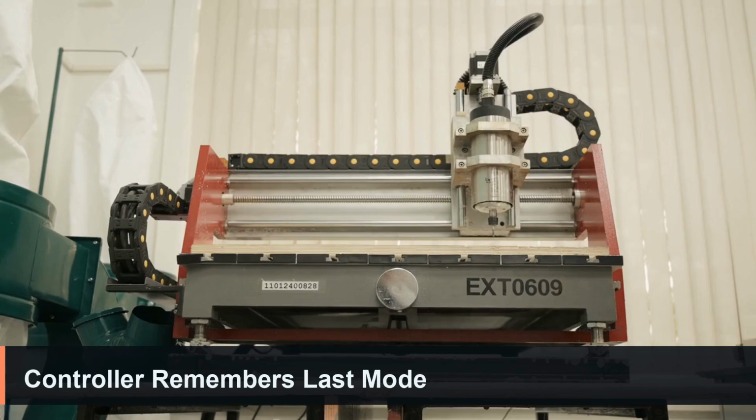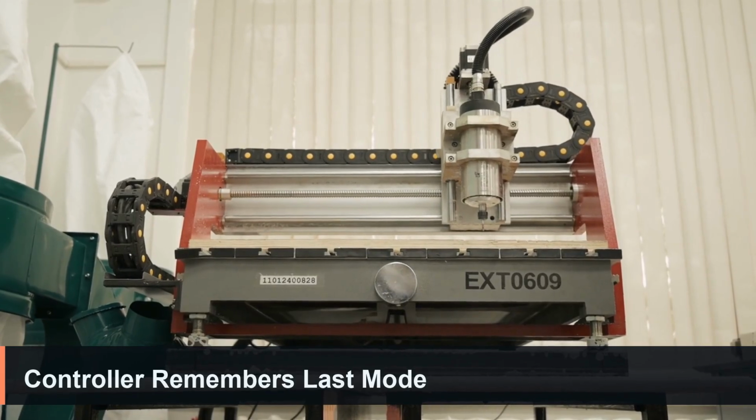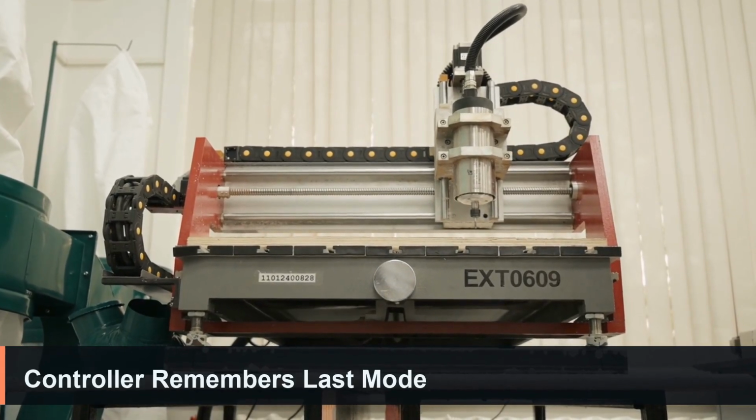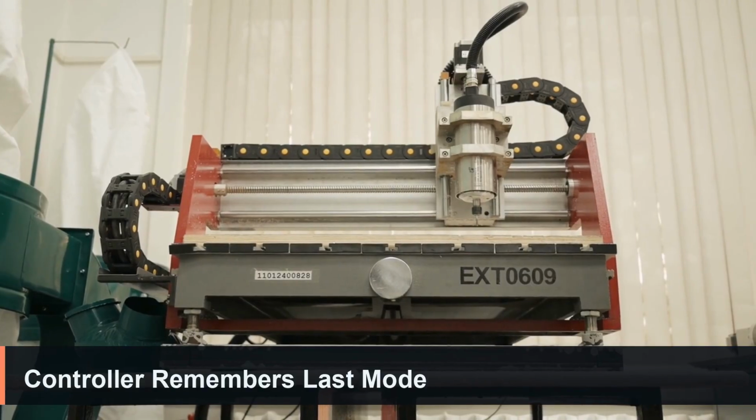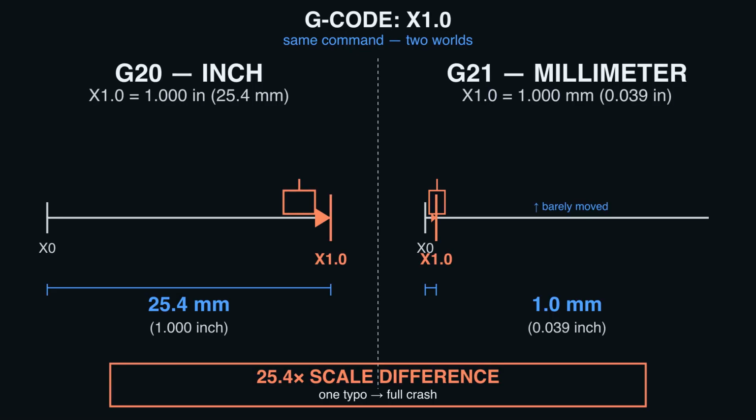follows. Here's the catch. The controller doesn't ask. If you don't declare units, it uses whatever mode it was left in by the last program. That's where the 25x disaster lives. Think of it this way. The program says move to X 1.0. In G20, that's 1 inch. In G21, that's 1 millimeter. Same number, 25.4 times the distance.